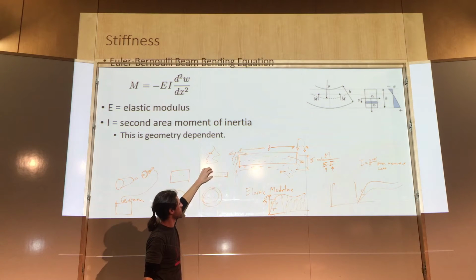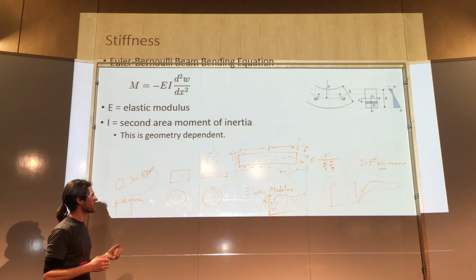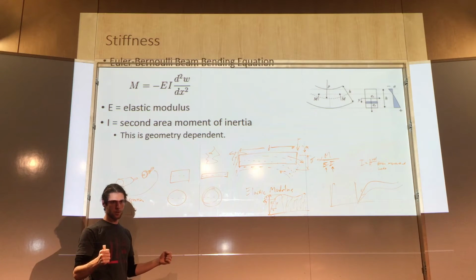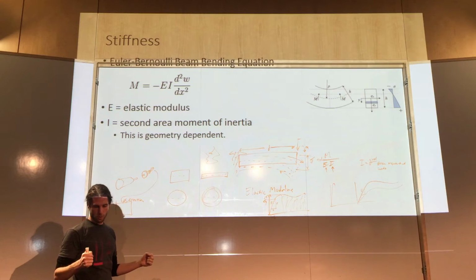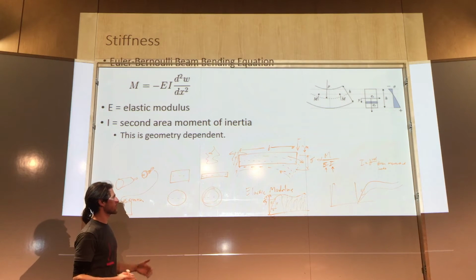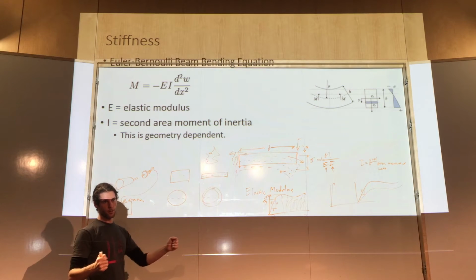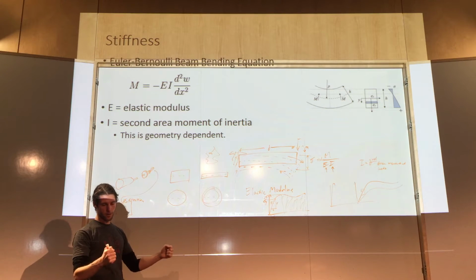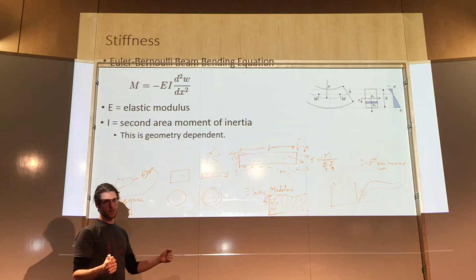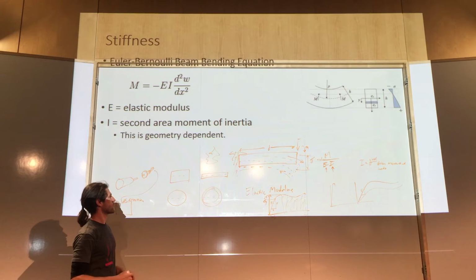The way I always think of it is it's essentially the same thing as the stiffness of your bearing stack. The further away I put my hands to support something, the less force I actually have to apply to make that system stiffer. It's the same thing as putting your mass further away from that neutral axis: for the same amount of force, it's more effective at resisting that tension. There are equations to describe all that, but you can just think about it.